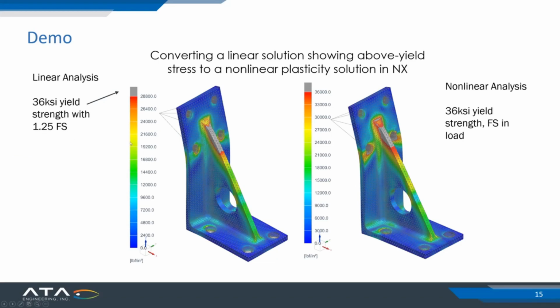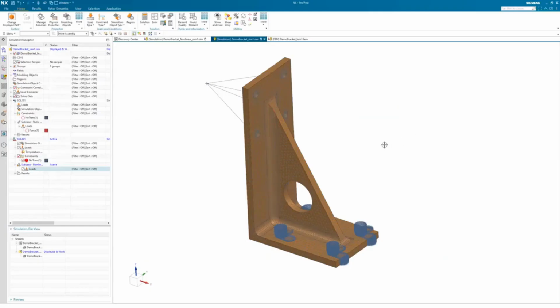So I was scaling my effective stress by dividing by my allowable to get the correct loading with my factor of safety. Because I'm doing a nonlinear analysis here in NX, I actually have to scale my loads up by the safety factor, so that when you are using the plasticity curve that you feed the model, the load goes all the way into that regime of plasticity.